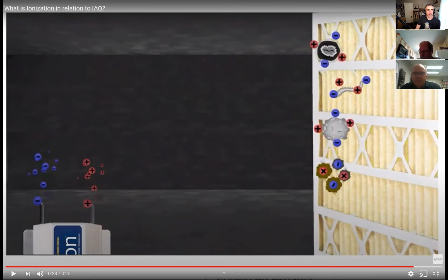Clarification. We have heard and seen products out there that are emitting UVB and UVA wavelength light. If you're aligned with CDC and ASHRAE, you're not meeting the standards. You should only be working with products that involve UVC wavelength lamps. Now, granted, that's all we have. That's all Ultravation moves, and most legit UV manufacturers and product manufacturers should be using that. It does give off some UVB, UVA, but the most destructive piece of that spectrum is UVC.